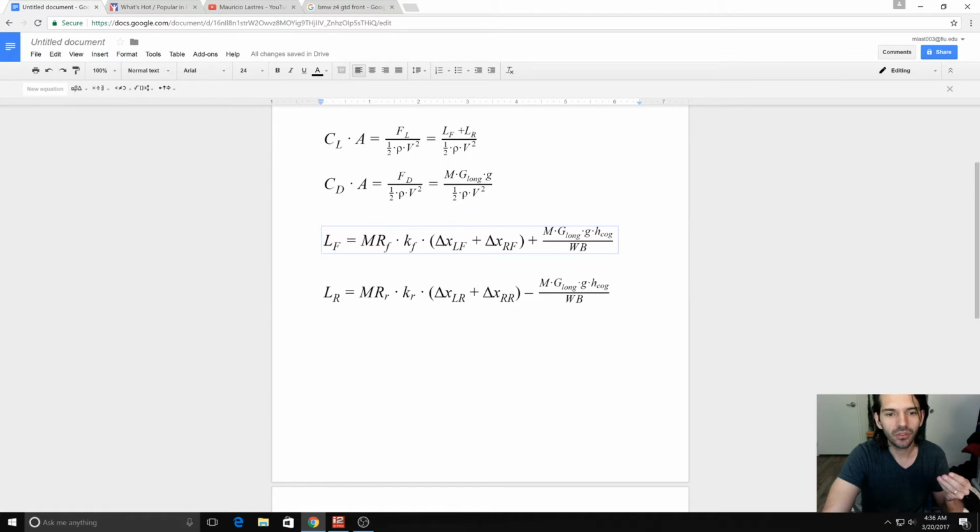And this also gives you a little bit of insight as to how weight transfer works. You'll see that there are two terms here, and in fact there are three types of weight transfer. And this one is independent of suspension movement. This is a geometric weight transfer, and it is only dependent on acceleration, and that's the only variable that's changing in time.